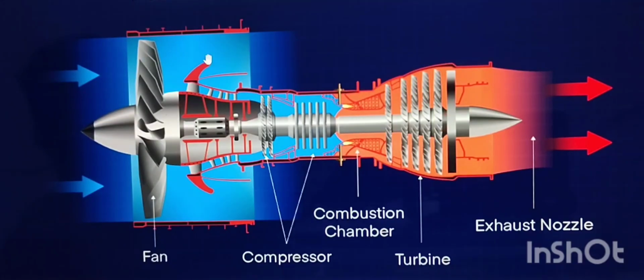Normally the air starter rotates this fan, and at the same time it rotates the compressor and the others. When the fan starts to rotate, because of the nature of the fan, the air will be sucked in by the fan. The sucked air will pass through the bypass, and about 25% will pass through the inner compressor.